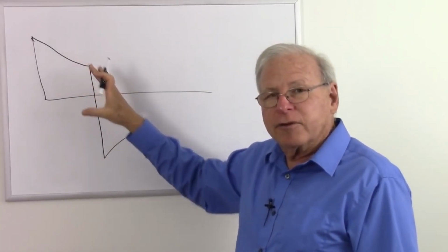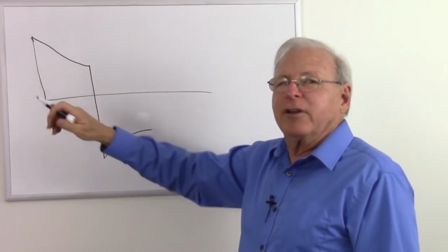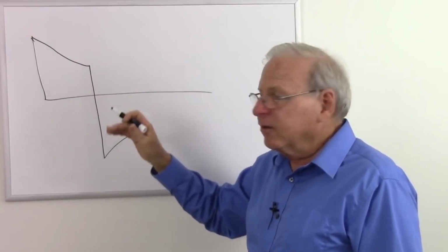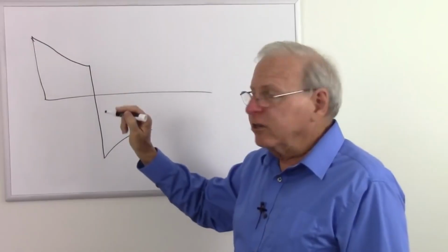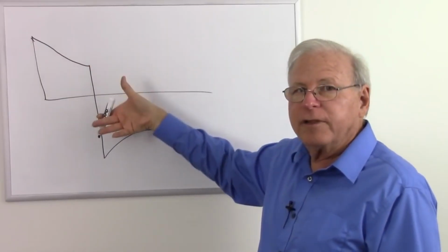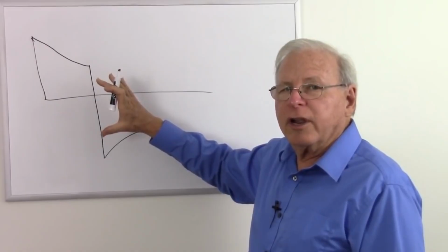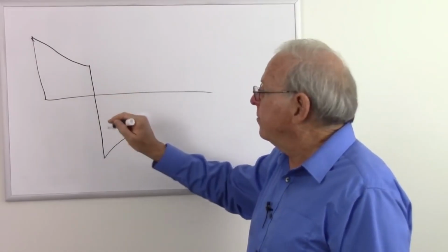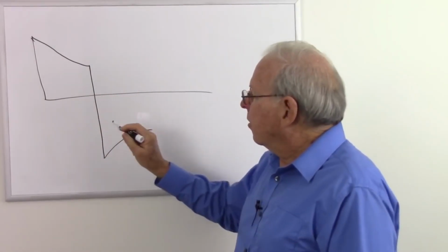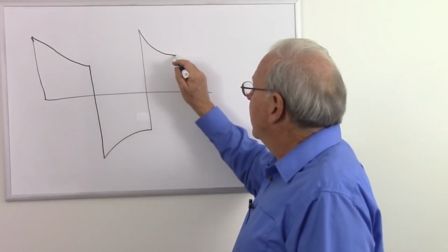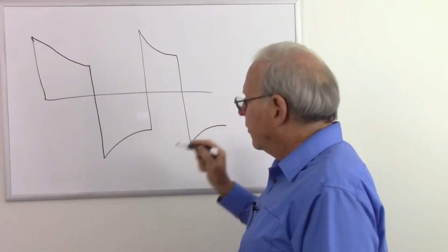So in the capacitor, it was the current that reversed polarity, which current flows this way, current flows that way. That was opposite polarities, or negative current. This time it's the voltage, as I showed before. That voltage on the inductor flips. When the current is going in, the voltage is one way, but when it is pushing the current in the same direction, the voltage flipped. And that's what's happening here. So as I flip those switches, I get voltage that does this, not the current.